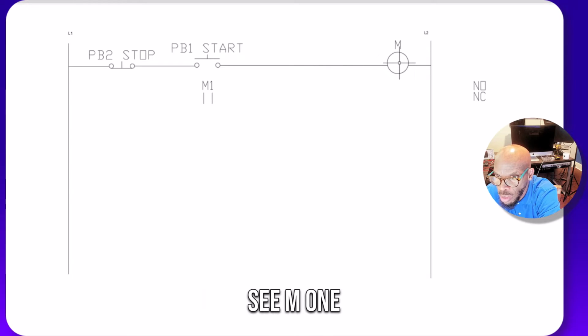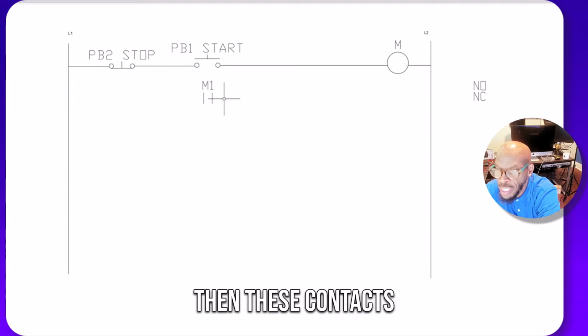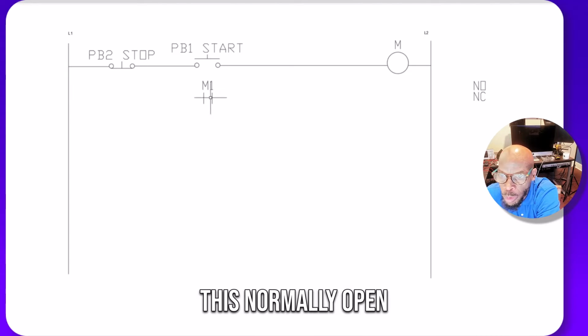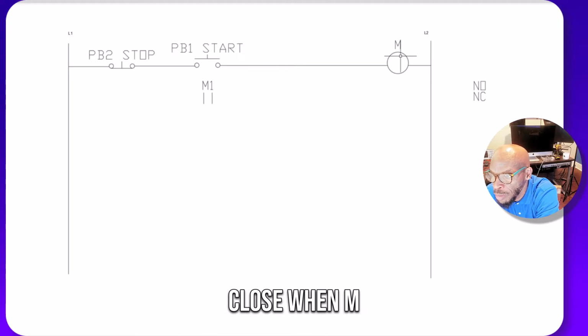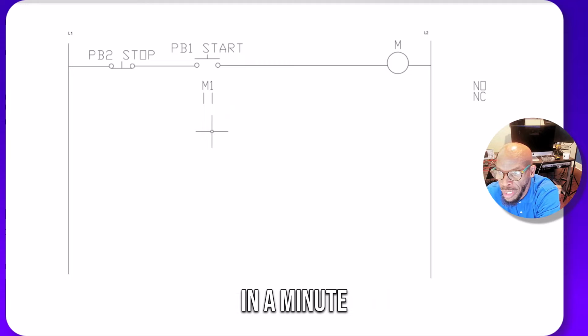So you may see M1, M2, M3, M4. All of those are part of M. So every time M changes, these contacts are gonna change. So this normally open contact is gonna close when M is energized. The normally closed contacts, which I'm gonna show you in a minute, are gonna open when M is energized.